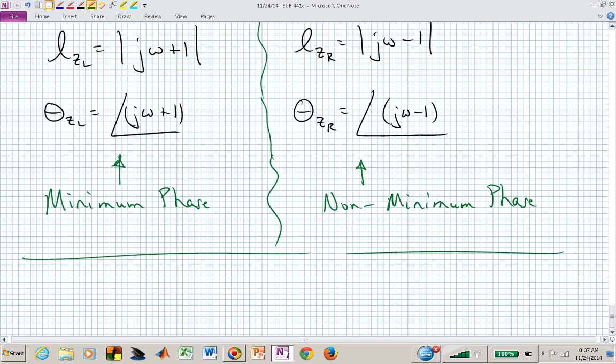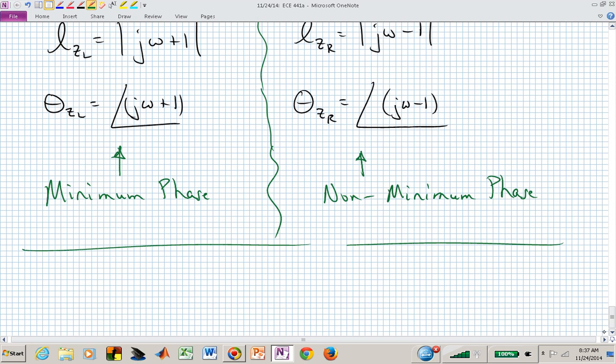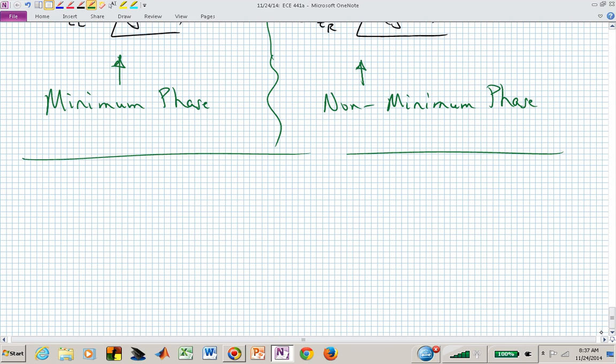As we've learned, if we have a zero there and we had a pole at the origin, you have an unstable system with a positive gain, don't you, in the root locus. So the non-minimum phase zeros do introduce more challenges, but to learn, for now, let's just focus on having minimum phase transfer functions. If nothing is stated, you can just assume that we're dealing with a minimum phase system. Is that clear?